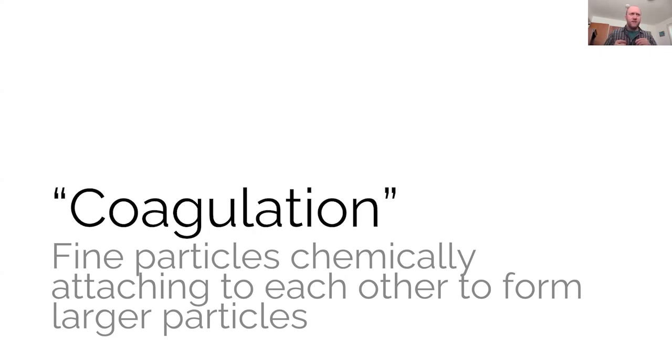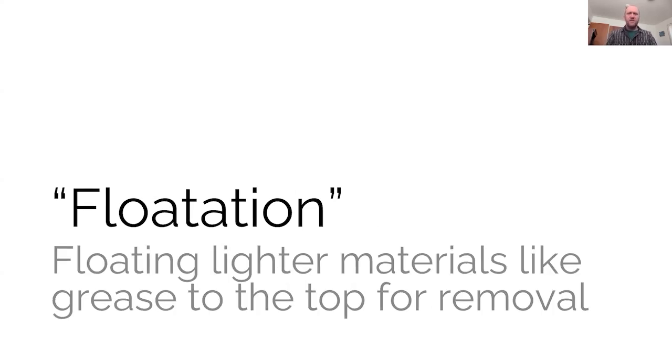So with coagulation, oftentimes a chemical is added, usually later in the process, not for the primary clarification, that will get rid of these negative charges, and then the particles will clump together and make bigger clumps that will settle out quicker. So that's the science behind that. And you'll regularly hear flocculation and coagulation in combination with each other, so just know that.